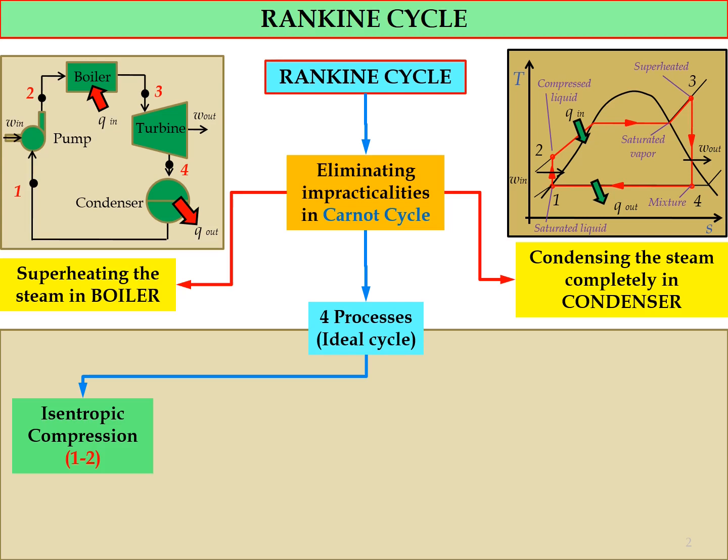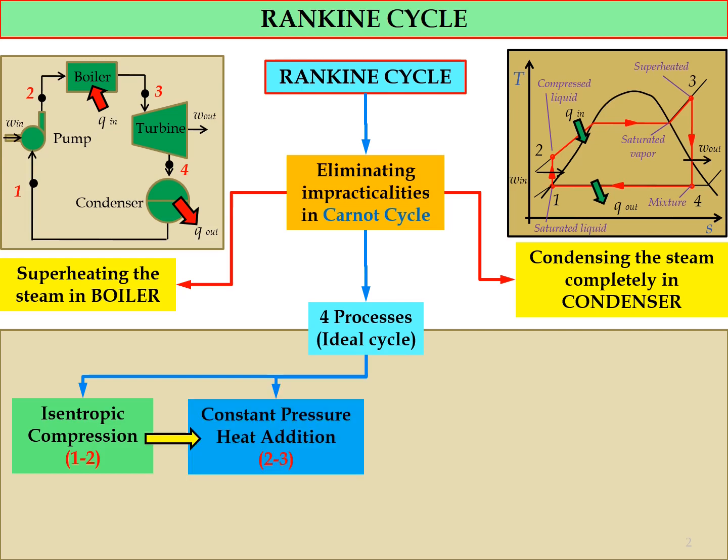Okay, so during the compression process we need to give work, that's why we have W in. During this process, the pressure will increase from P1 to P2, and the temperature also will increase. Okay, the second process we call the constant pressure heat addition process.